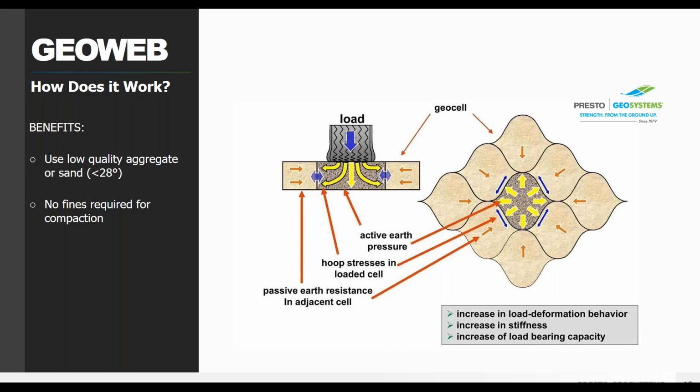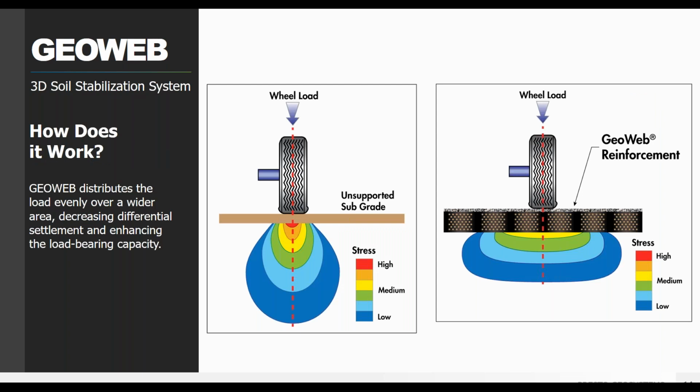By spreading out the load in a classic granular fill approach, you can reduce the compaction of the near surface soils, but only with the GeoWeb cellular confinement can one ensure that no lateral shifting occurs, so you're not going to get those ruts. And the mattress effect reduces the stress reaching your subgrade. So all of these things work together. We've done a lot of testing to show how this all works, and we'd be happy to discuss that with you if you do have questions. But that's about as much as we're going to get into today.